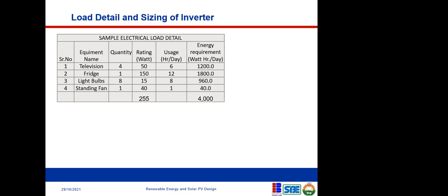Even though you've done all of this loading, you still give your tolerance and your margins. So now we know what the power demand requirement would be. Based on the hours of usage, we can now establish the energy that is required. So here we have established that it requires 4,000 watt hour per day. So let us now size a solar system for this kind of a system.